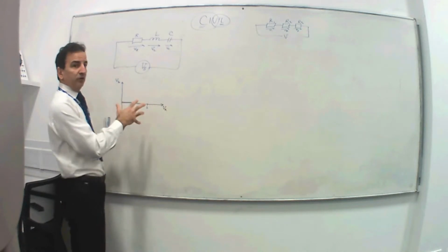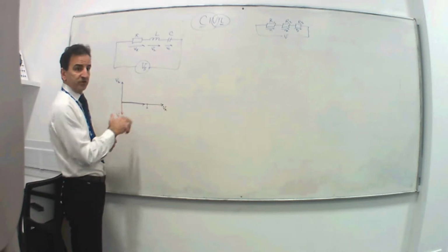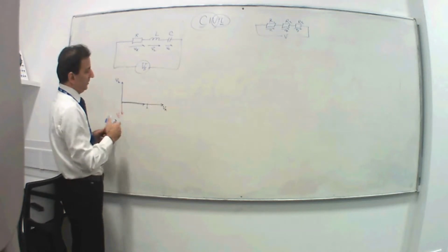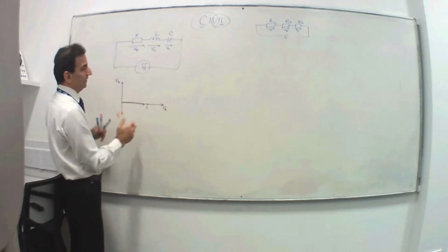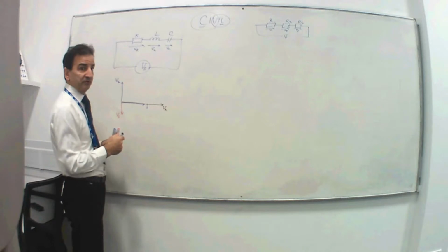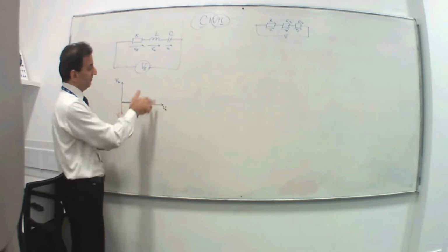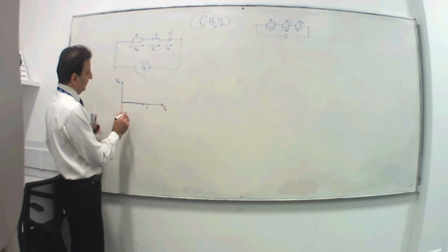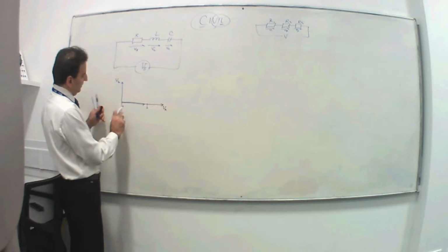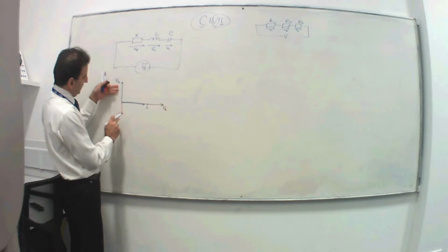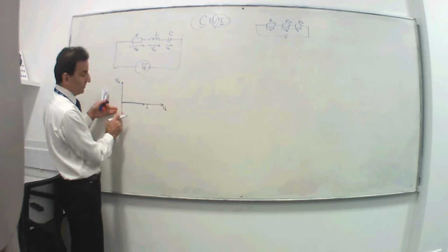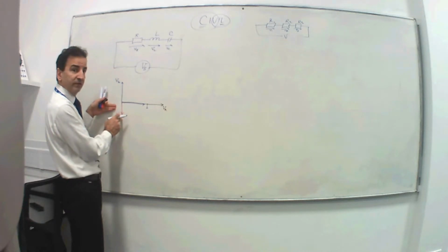Now, to find the overall voltage, the voltage of the supply, you have to add all these three, the vectorial sum of all these. To do that, the first thing you do, you get rid of this. You've got two phasors 180 degrees away from each other.